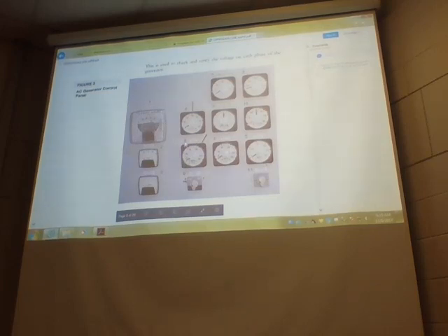If you look on these 3, phase A and phase B are pretty close to being the same. Phase C is a lot lower. In a 3-phase system, you want to try and keep those 3 phases balanced as much as possible.